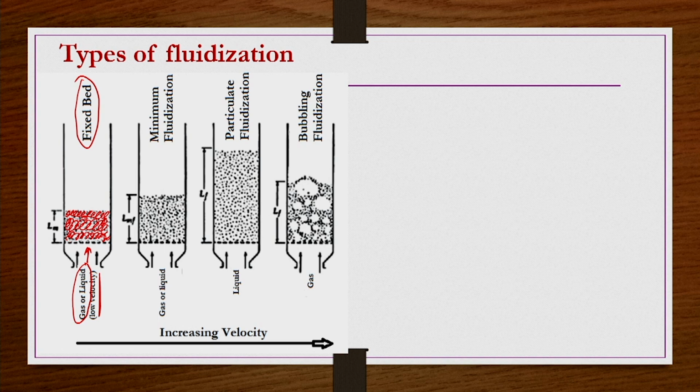Under such low velocities we can use the Ergun equation without any difficulty, even if the bed is not packed or constrained at the top. This is the free board area that we have already seen. The free board area would be available for the particles to move into if they are moving up. But subsequently, if you gradually increase the velocity,